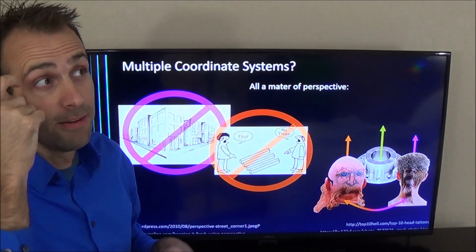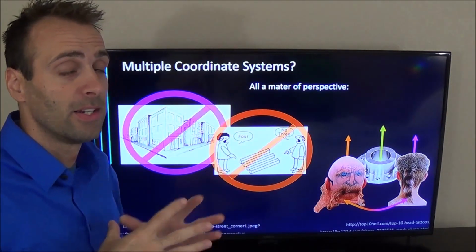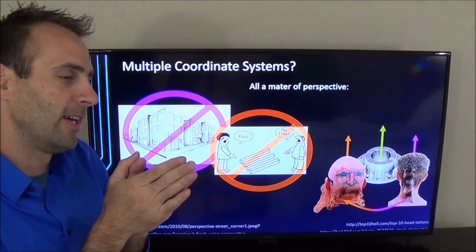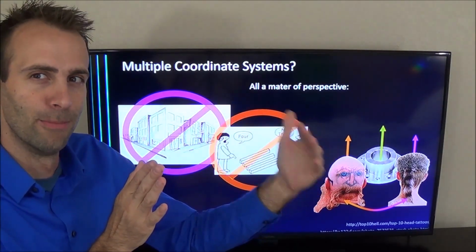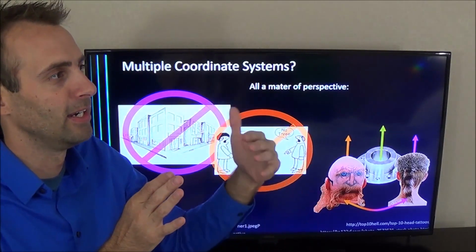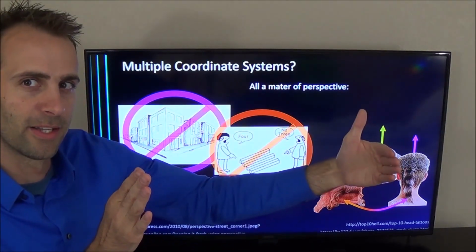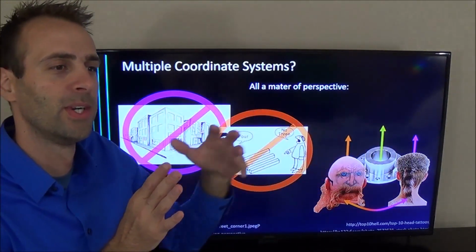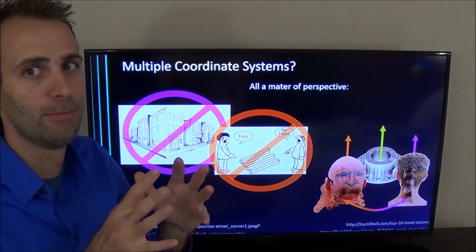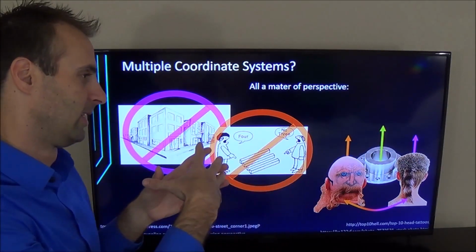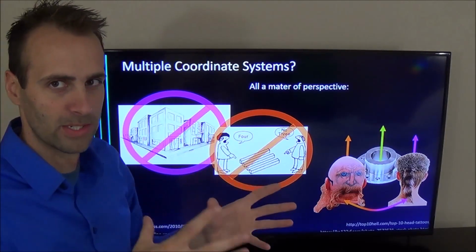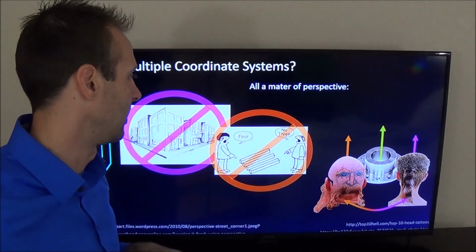And if you look at linearity, right? If I say I want to move 1 inch and I tell my axis to move 1 inch, but it moves 0.9999, I need to push that axis a little bit farther to get it to 1 inch. Yeah, that's a scaling issue, but that needs to be completely separate from the coordinate system and things like that. And we'll talk about that again.